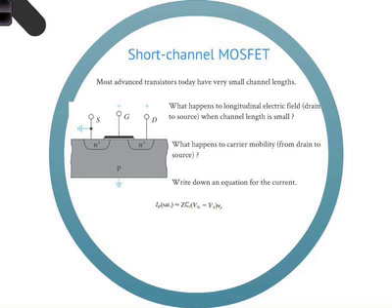So I, what did we say? We had a charge, Qn, times mobility times the field, Vd over L, more or less. Right? The Qn can be written as the capacitance of the oxide multiplied by the gate voltage, minus whatever is required to create the channel, which is basically the threshold, Vt.